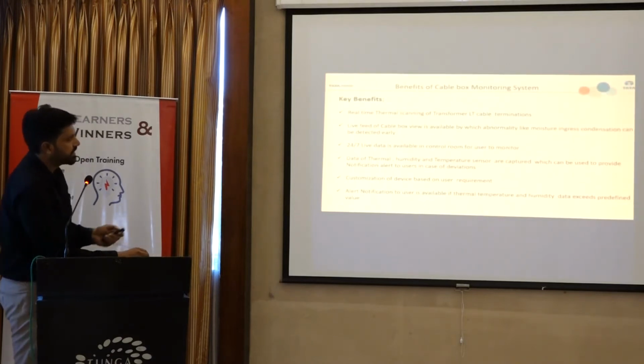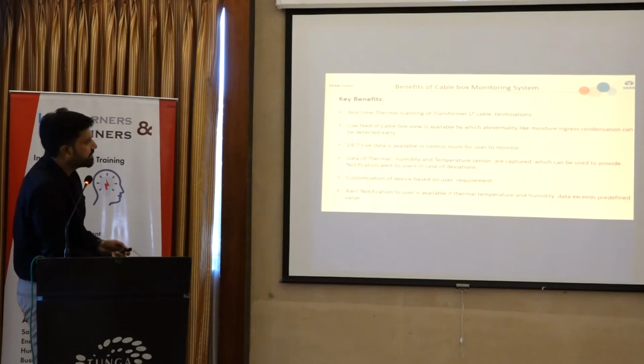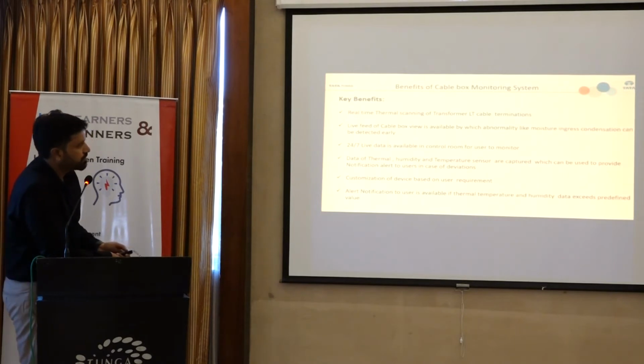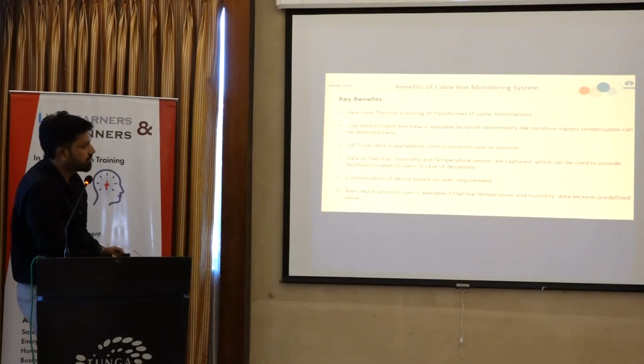The benefits of this cable monitoring system are that real-time thermal scanning of transformer LT cable terminations is available. A live feed of the cable box view is available, by which abnormalities like moisture ingress and condensation can be detected. And 24/7 live data is available in the control room for the user to monitor. Data of thermal, humidity and temperature are captured, which can be used to provide notification alerts to users in case